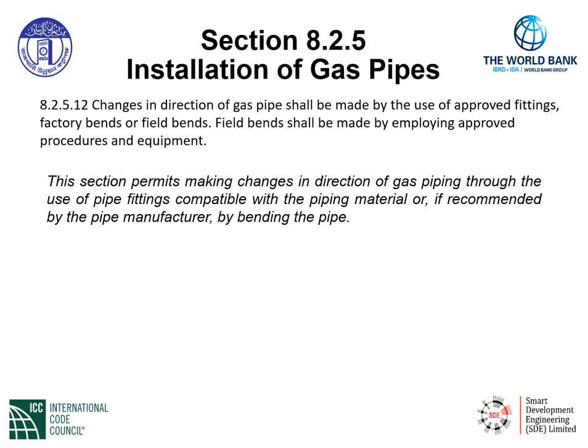The correct pipe bender for the correct outside diameter of pipe ensures that when the gas fitter properly attaches the pipe bending apparatus to the pipe, the pipe, once bent, will be free from any kind of internal radius buckling or kinking that may alter the flow within the system.